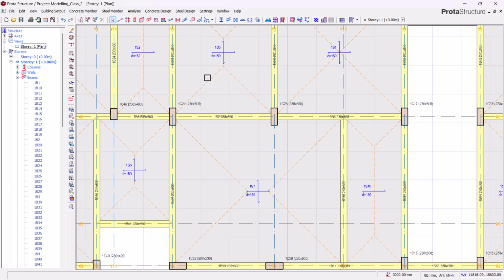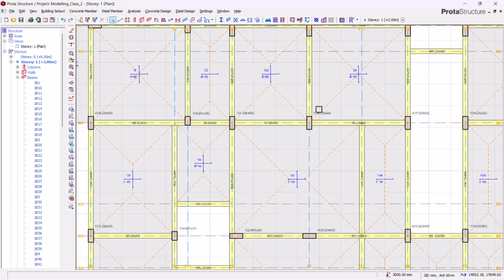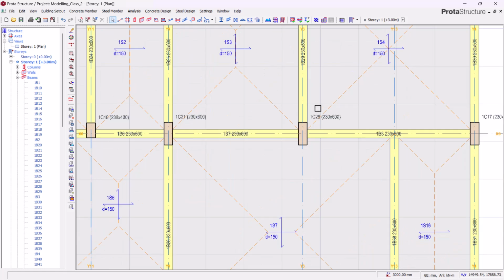We should not just reduce our column sizes because we want to impress the clients or because we want to show the clients that we can do a very cost-effective design. What should guide our increment or decrease of our column sizes is if it has satisfied the loads that are implied on it, speaking about the vertical load and also the horizontal loads. All right, so we run our analysis and check if they are not sufficient, then we have no other option than increasing the size of this column.